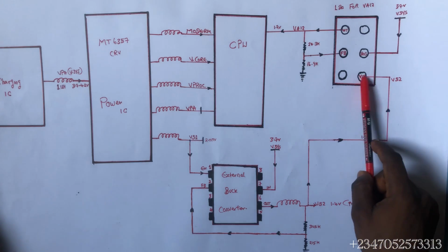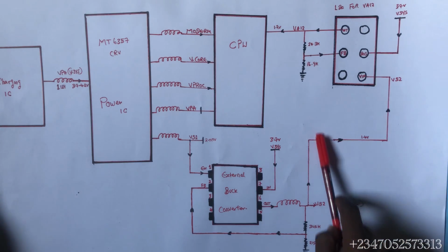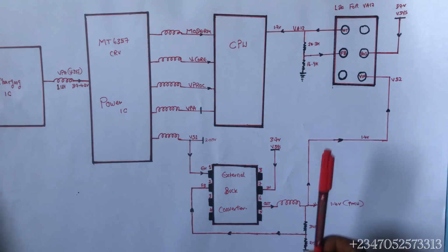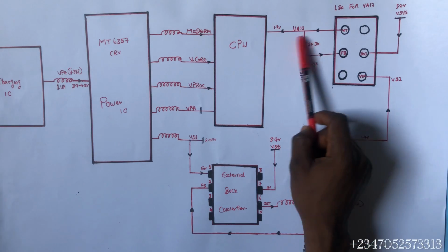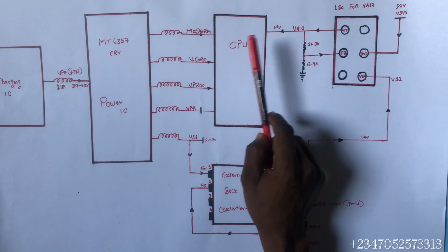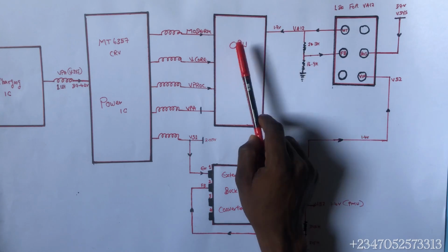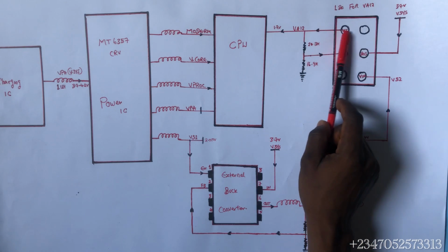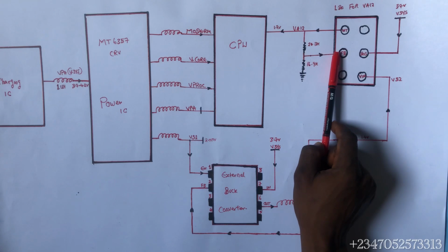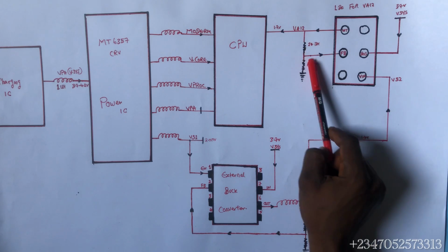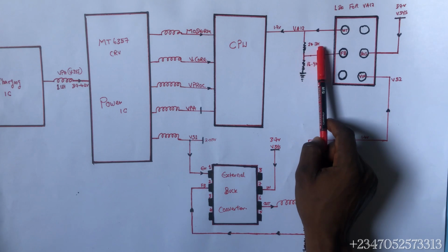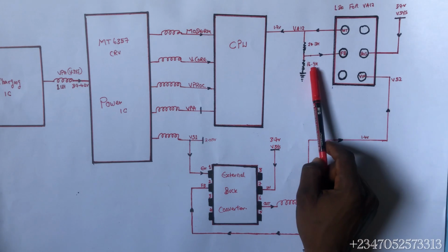Now it will enter, there are capacitors on this line, so you will test to see if the voltage has entered. Now if this IC is not creating this 1.2 volts, your phone will not turn on, because this 1.2 volt goes to our CPU. When this line creates this 1.2 volts, there is a feedback line also. There's a divided circuit here. This R1 is 24.3k, this one is 16.9k.